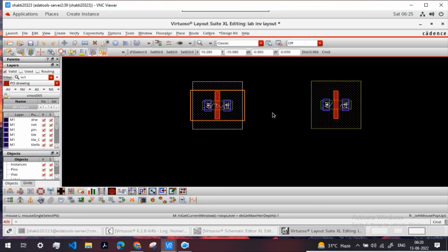So for making the PMOS inside the P-type substrate, we first need to create an N-well, which is a region of N-type substrate, and then there we dope P plus source and drain to create a PMOS. For NMOS, I don't need any P-well as such, because the whole black region is itself P-type substrate.